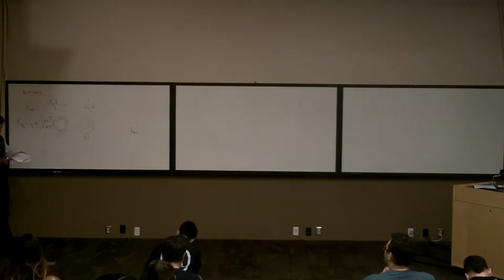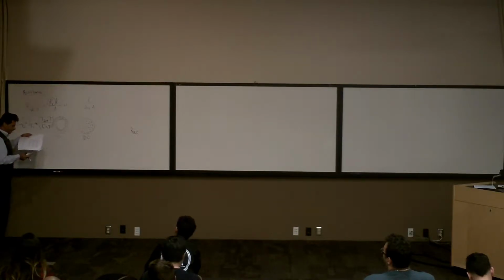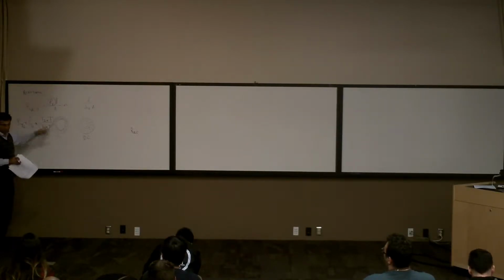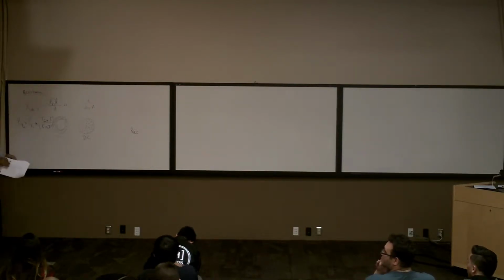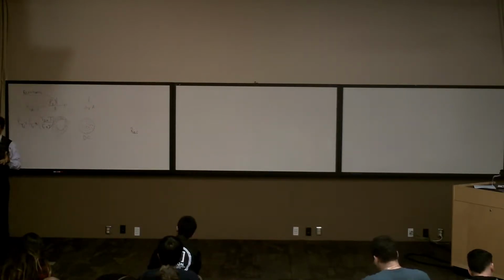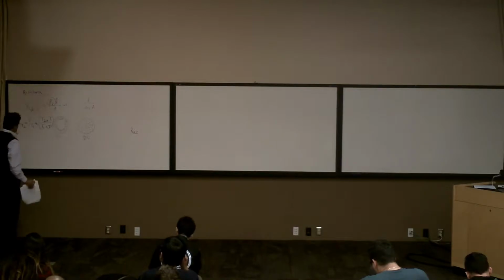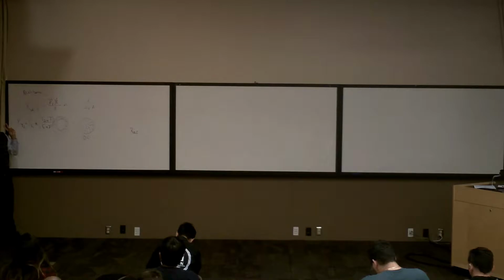Then if you look at your book, this table, for example, Table 4.3 on page 175, it gives you T. For example, copper is 234.5. For aluminum, for example, it is 228.1. So this T is a constant number for these different materials. Now you can see if the temperature goes up, the rho is going to go up. So the rho goes up means the resistance is going to go up. So this is another element of the resistance.